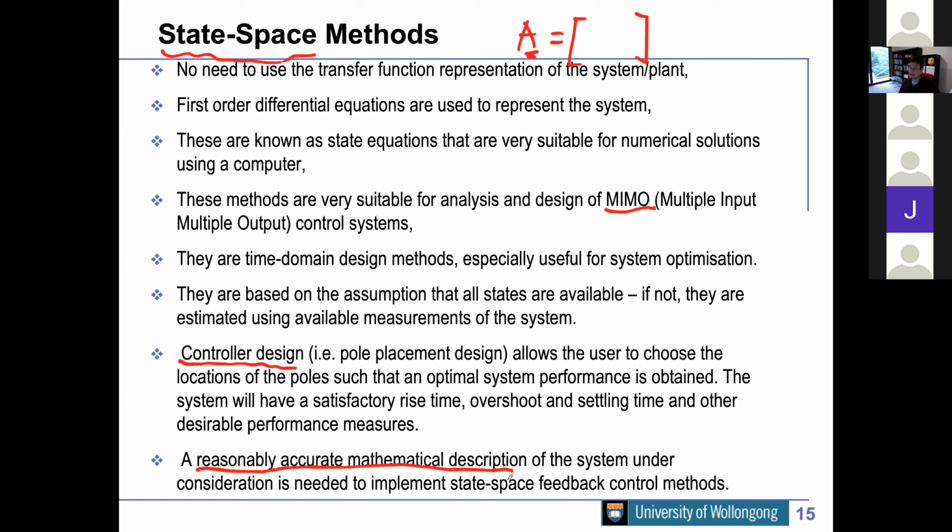However, with a PID, just doing classic control, you don't need to know it. You can do trial and error. With state space, you can't do trial and error because it's just too complicated. You must get an accurate model. So that's only suitable for things that are worth doing, for things that are so complicated and the performance requirement is very, very high, so the cost sometimes becomes less important. Otherwise, you go to classic control.